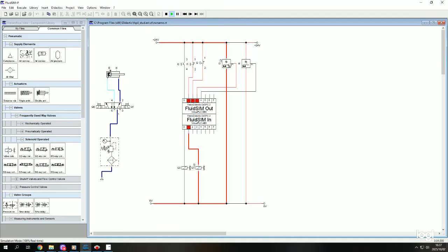So the solution that you have on the lab guide there is not a true reflection of the actual statement that we have in exercise 5, because exercise 5 doesn't automatically retract. It says you need a second push button to retract. But the memo that we have there is this one, so it's not the same thing. I hope you are reading through your statements and challenging the statement. Why am I having 2 proximity sensors while my statement only says I retract with another push button?